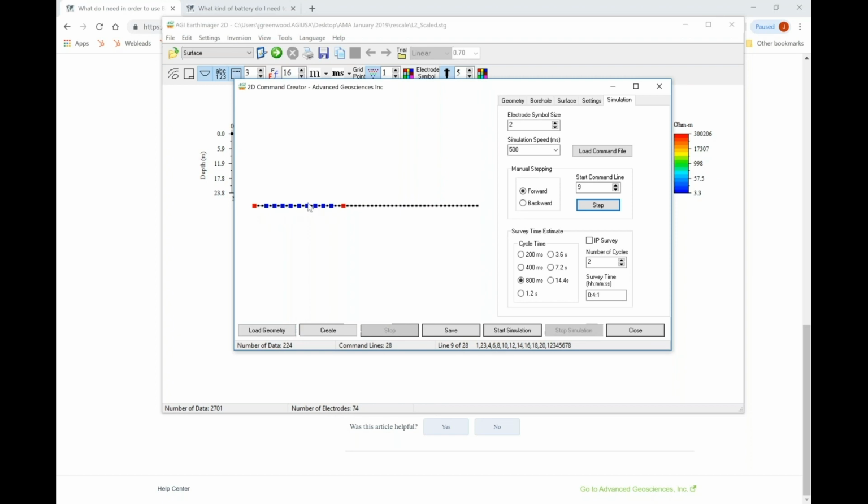But we are sampling it in the very highest signal portion in between the transmitter and receiver, and in full 8-channel mode. These electrodes here that I'm pointing to are actually Wenner. And then this would be something close to Schlumberger. And then out here is gradient. So in 8 channels, we're getting basically Schlumberger, Wenner, and gradient all together. So it's very efficient, quick, low resolution, but high signal. So this can help fill in gaps if your dipole is missing it.